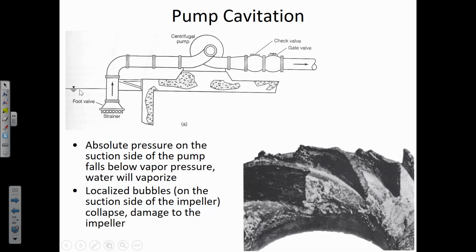All right. So here we've got a free surface of water, and that's where the pressure is 0. So the pressure is 0 here. It also means that the pressure is 0 inside of that pipe. So if the water is going to be moving towards the pump, then that means we're starting at 0 gauge pressure, and now the pressure is getting negative, more negative, getting closer and closer to the vapor pressure of the liquid.